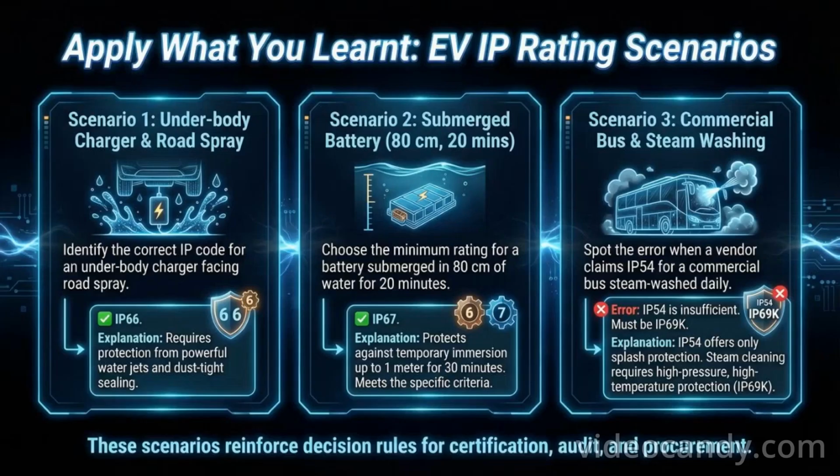Fly what you learned. Identify the correct IP code for an underbody charger facing road spray. Choose the minimum rating for a battery submerged in 80 centimeters of water for 20 minutes. And spot the error when a vendor claims IP54 for a commercial bus steam wash daily. These three scenarios reinforce decision rules, prepare certification engineers for audit questions, and give procurement teams confidence to challenge non-compliant suppliers before hardware is locked into vehicle programs.